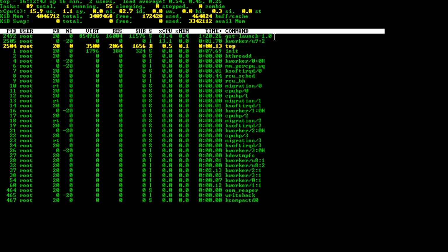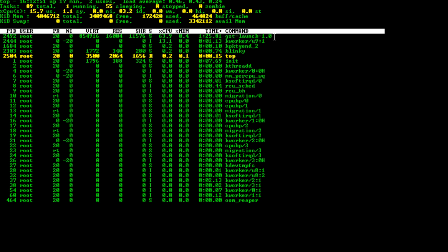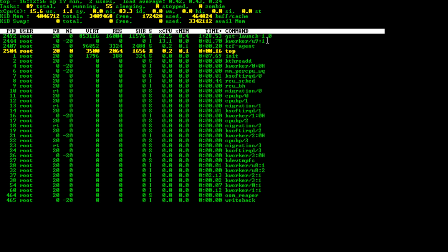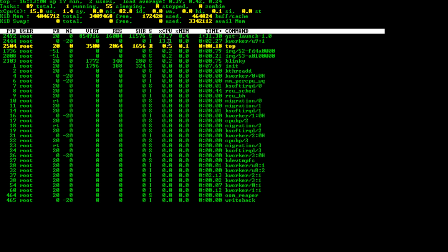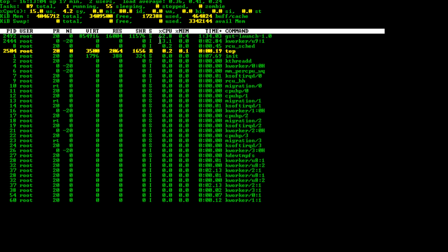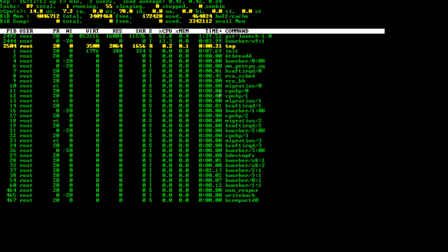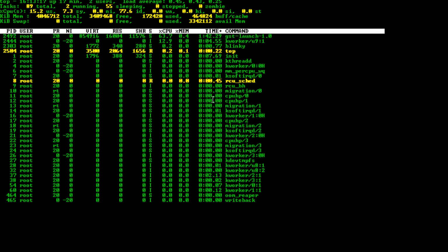Then that's also coming back out of the encoder, going through RTP, and then packetization over UDP and sending out over the network. So 64% total for that whole data processing. And then we've got this kworker thread that's about 12 to 13%. What that is servicing is the USB interface, bringing data in from the webcam. And then part of that gst-launch is also sending that back out to the DisplayPort. So I just wanted to highlight, that's what the CPU utilization looks like for 720p, 10 frames a second.